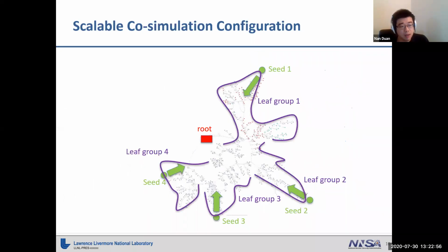What we did is define those seats as the location of the restoration units, and also you get a collection of the edge nodes of this entire grid. And some graph theory work is used here as well to remove those cycles in the distribution grid. Since the distribution grid essentially is very radial, but there could be occasionally brief cycles, removing them will facilitate easier translation of the hierarchy of the subgraphs.